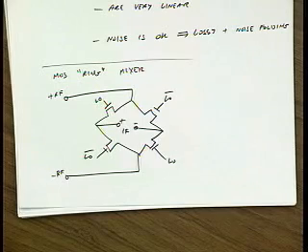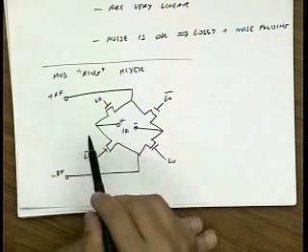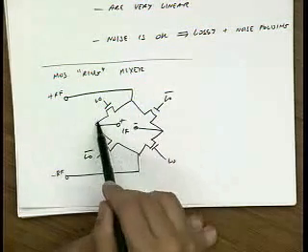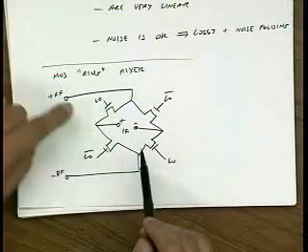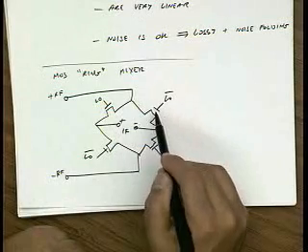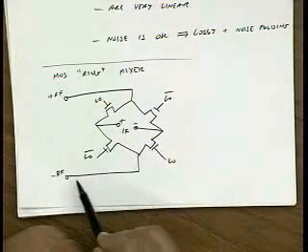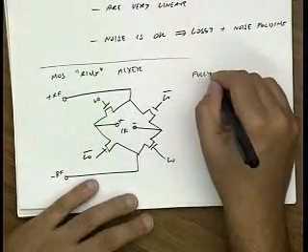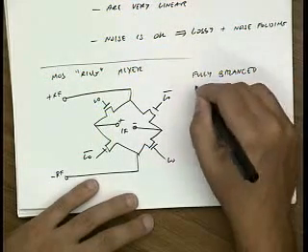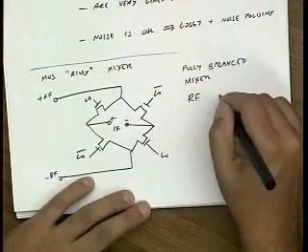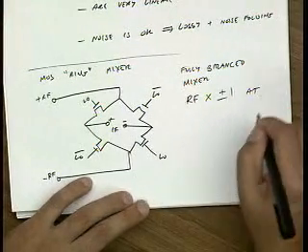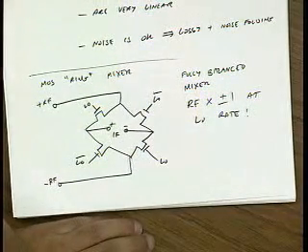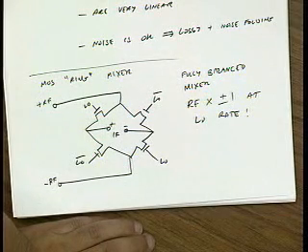And you can see that this circuit looks like, again, the equivalent circuit is that when LO is high, let's say, then RF is connected to the output through this network, right? And when LO is low, then these 2 transistors turn on, and the RF is supplied to the output with negative polarity. So again, this is a fully balanced mixer. RF gets multiplied by plus minus 1 at LO rate. Okay? So it's a fully differential version of the mixer that we just looked at.